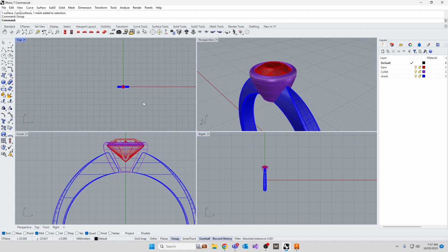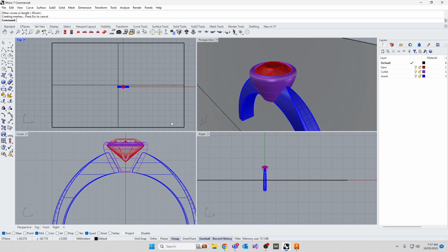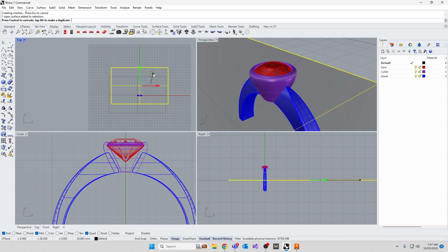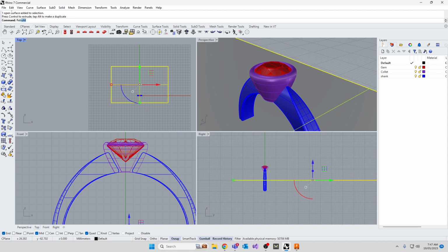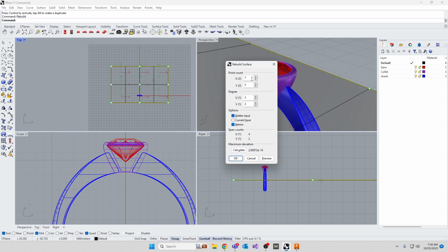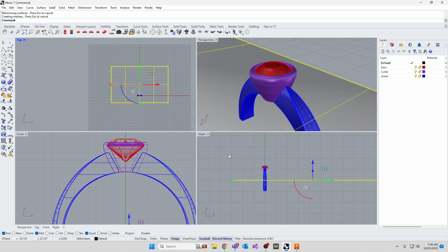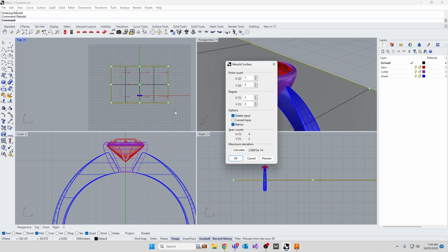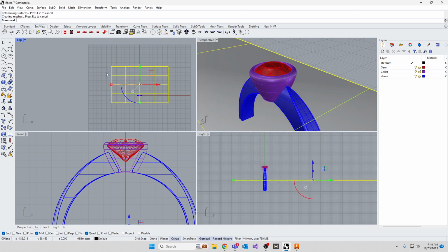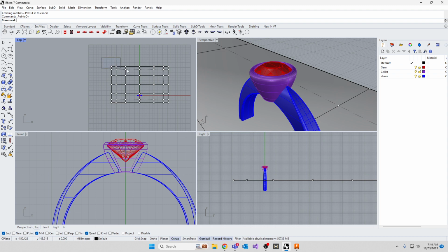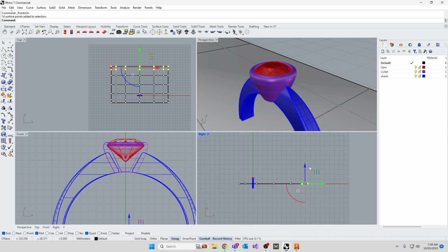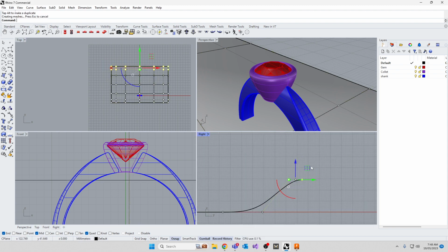Give yourself a plane to render on. All right, so I'm going to draw a plane out here, like that. All right, move the plane backwards, something like that. I'm going to rebuild the plane to have a few more points. Whatever that is, seems fine. All right. Actually, it was the wrong way around, so Control Z and redo, and I need 7 in that direction. Okay. And what I want to do is turn on the edit points for that plane, and we're going to create an infinite plane in the background so that we can't look over the edge of the